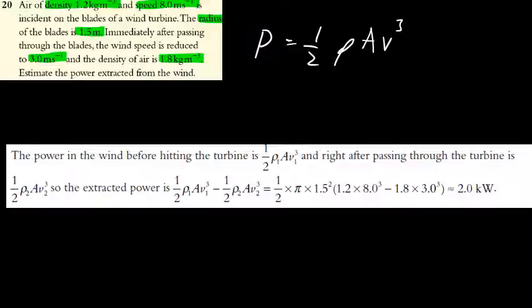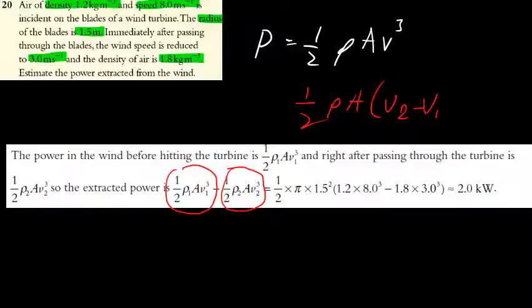Maybe that's why they do the previous question like that, because they want to reassure you that the air particles will not stop right away after the turbine. So this question is more about calculation. You can simply apply the equation, and then by substituting the V before and V after on each equation, pay attention that you cannot do like this, V2 minus V1 and then to the power of 3.